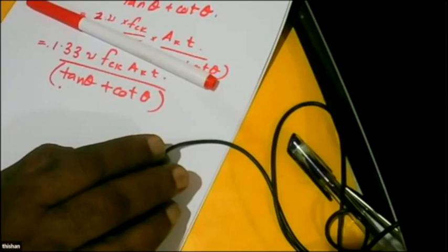But if you look at the standard textbooks, they all recommend the use of a beam element as a rigid arm. If somebody wants, they can do an experiment and see whether it works. But generally, there's no harm in using rigid arms made of beams, because that is what textbooks recommend.